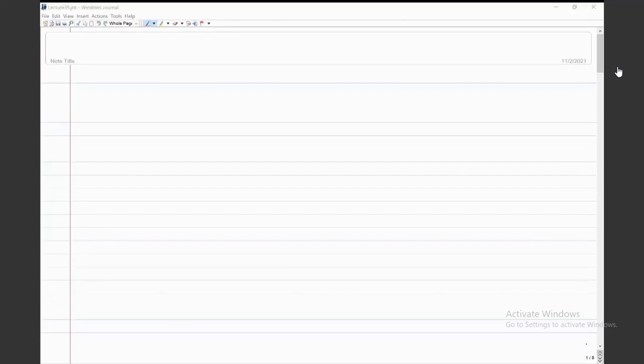Initially there is a gap, so you have U3 and U4 on the other side. That initial gap I have taken as G. When you apply the load, U3 is increasing. When there would be a load F star, U3 will be equal to G and U4 is 0. At that time the gap will be closed. Subsequently there would be deformation at node 4 also, so U4 will also be non-zero. But the values of U3 and U4 will always be such that U3 minus U4 minus G equals 0 when the subsequent deformation happens.